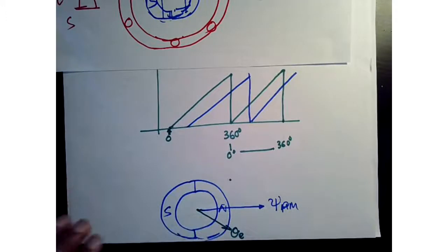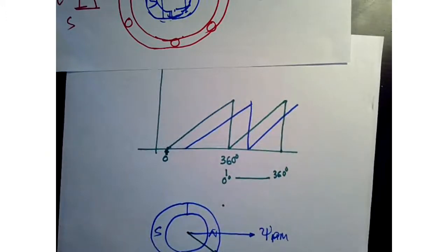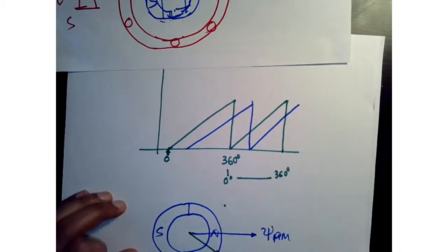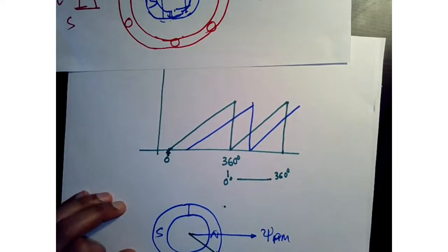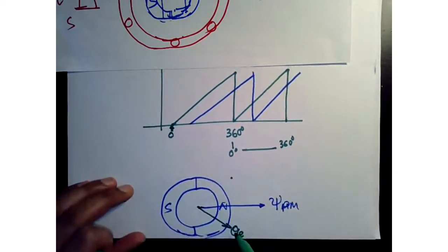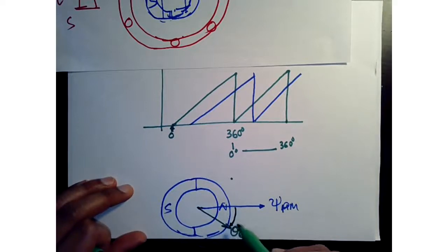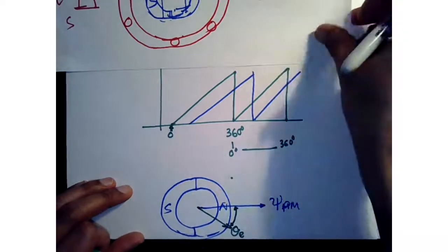However, the problem is this is what we are using to orient our stator flux vector. And if we use this as it is without correction, we have a constant offset, and we are not optimally placing our stator flux vector. So can you propose something to fix this?